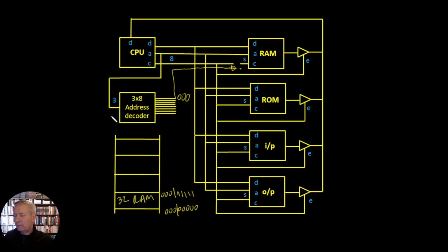So if we put an address onto this bus that's anywhere between these two values, it will always talk to just this device. Because this control line here ensures that it only talks to just this device. We dedicate this line to this device and it tells it that's the device you talk to between these two sets of addresses. And you can see it just forces it to do that because this goes high whenever these 3 bits here are 0, 0, 0.